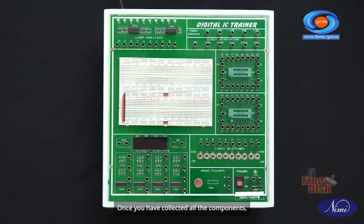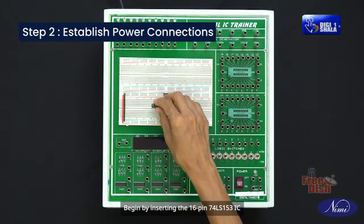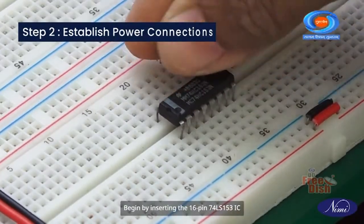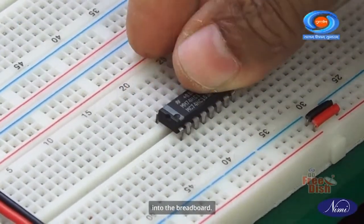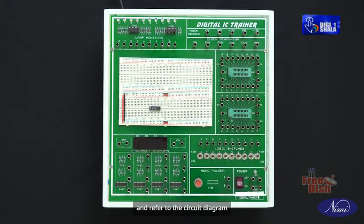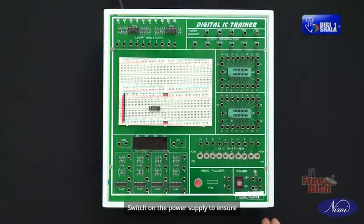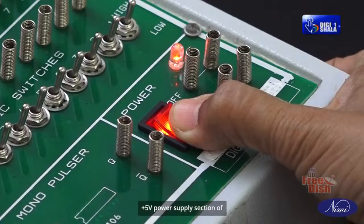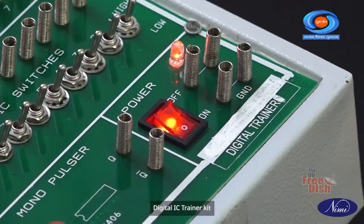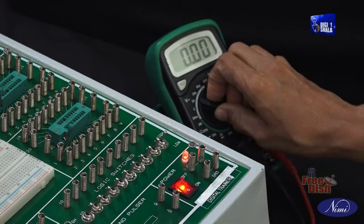Once you have collected all the components, prepare the breadboard. Begin by inserting the 16-pin 74LS153 IC into the breadboard. Make sure all pins are properly aligned vertically and refer to the circuit diagram for accurate placement. Switch on the power supply to ensure the plus 5 volt power supply section of the digital IC trainer kit is working or not using a multimeter.